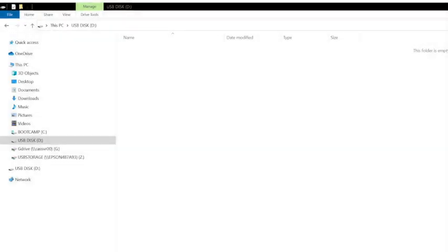Okay, we're now in Windows Explorer, File Explorer, and we're just going to program the USB stick or the SD card to actually make a simple program. In this case I'm using a USB stick, and you'll see this on the left hand side. So we need to create a few folders on the card. For this example I'm creating a system where I'm going to have 2 messages starting from a closing contact. The player will just sit in standby when it's switched on until the closing contacts actually activate the message. So I'll show you what to do on the card.